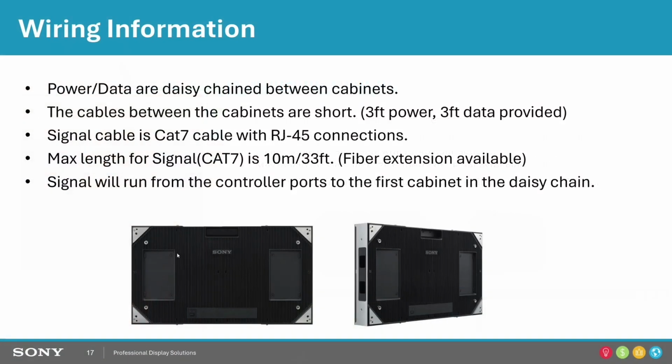See these two covers? Those covers need to be removed before you put them in the wall, because you cannot remove them once they're installed on the frame, unless you've got rear access, which most of these installs do not. So that's a note to be taken. Be sure for your home run cabinets that you remove those covers. It gives you access for your home run feeds.